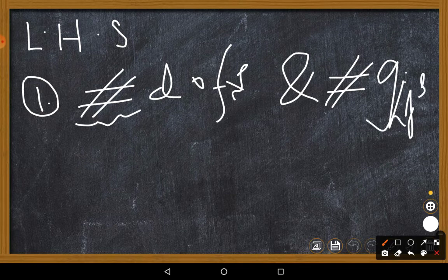These q_j might not be Cartesian, but they must pass your test of independency and completeness, and the system must be holonomic by choosing such q_j, and that makes the coordinates q_j generalized. This is the first thing. You first determine the number of degrees of freedom, in how many different directions it can move, and perhaps the second thing you find is the number of coordinates you are using and what coordinates you are choosing.